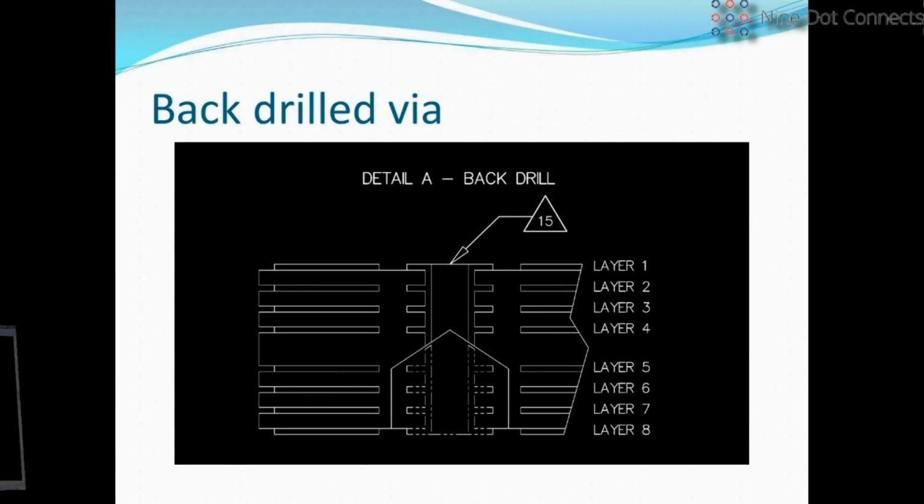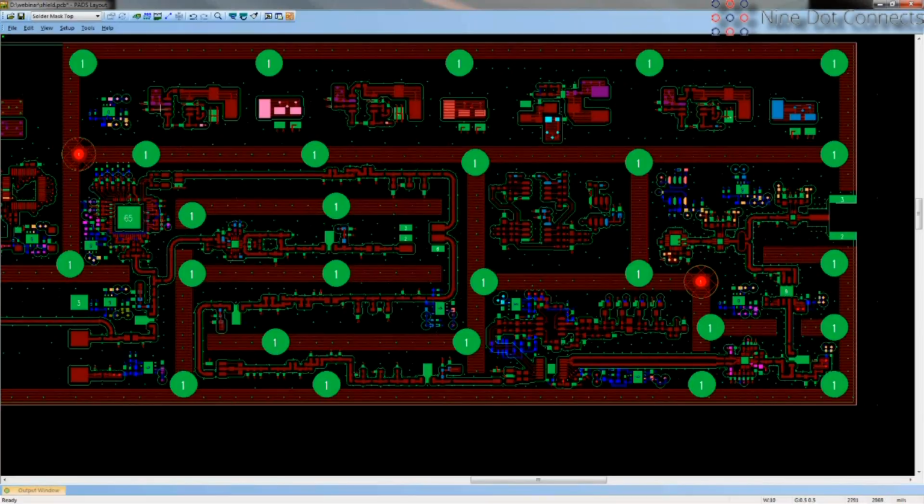Let's say, for example, one of these devices here. You'll notice that most of these are closed loop. They provide ground underneath the component, and I would encourage everybody, if you're using power supplies, download the data sheets for them. They oftentimes will make available to you right in that specification the good practice or desired practice of location of components and how to make a good circuit, and they'll show a good depiction there. It's critical that power supplies are your worst offender when it comes to generating noise into a circuit.